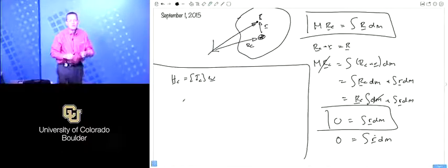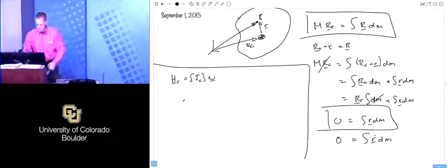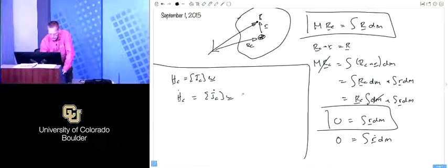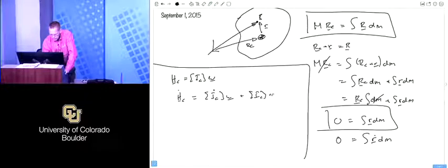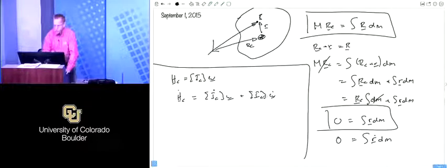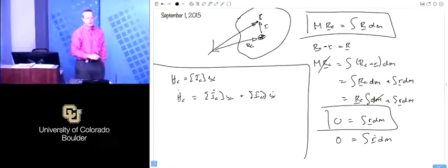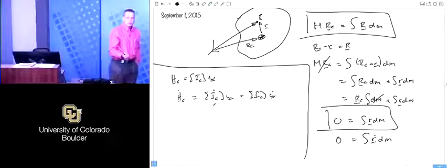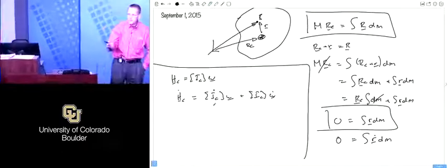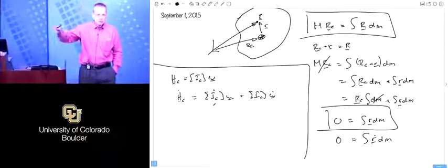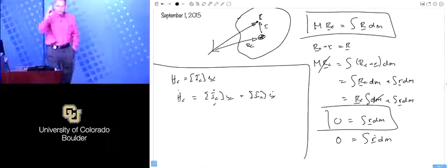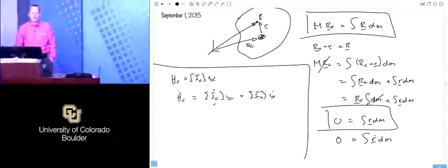So that was the key reason why we've chosen here to use, again, the transport theorem, because here, if I take h dot C, you would end up with I_C omega dot plus I_C dot omega, like that, right? And it gets much more complicated, because how do you get the I_C part? Well, we have I_C fixed in the body frame, but then you have to pre and post multiply times the DCM. So with the chain rule, you will have two DCM dots, which were minus omega tilde DCMs, all plugged in. And in the end, you always get the same answer. Hopefully, it's the same physics, but it's a much longer way to get there.